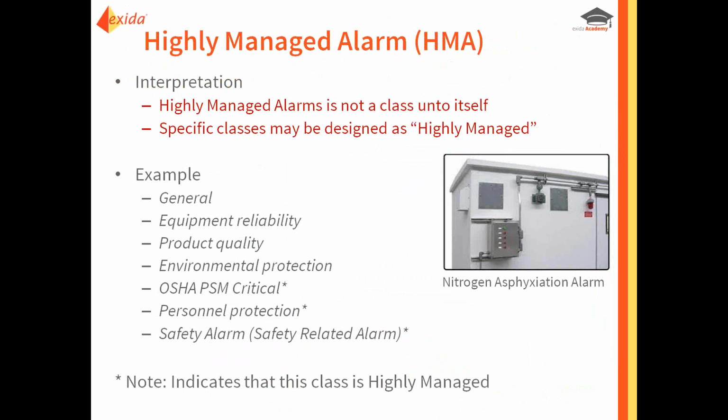And if you think about the picture that we see here, this example of an analyzer shed, that alarm working to indicate that there's a low oxygen environment in the shed is really important. If you were to walk into that shed in a scenario where that alarm failed to work, you may never walk out. You could end up dying if that alarm does not work. So certainly the way that alarm is treated from a management of change point of view, you don't want people messing with how that alarm works, that's for sure, because people could get hurt or die if it's not working the way it's supposed to.